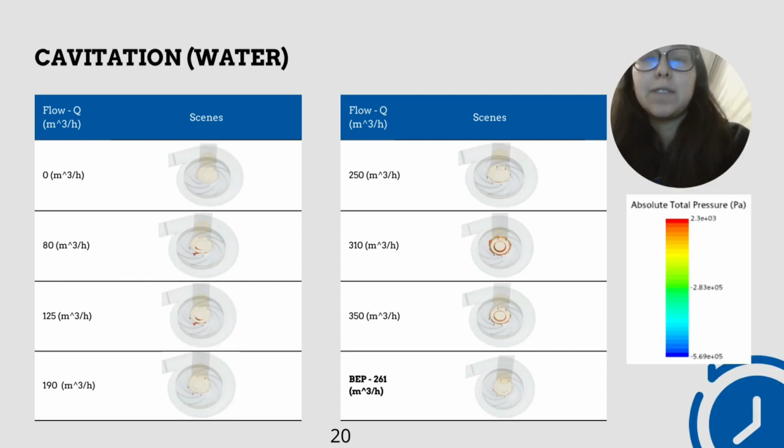Also, we made a cavitation analysis. In this analysis, we put as a maximum absolute pressure of the pump the vapor pressure of water. If the pump presents this pressure, the pump can cavitate. So we can see that in 4 of our 8 simulations, there can be cavitation.